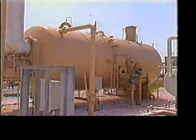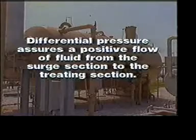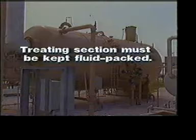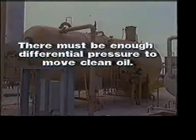There are several reasons why higher pressure is maintained in the first two sections. First, the differential pressure assures a positive flow of fluid from the surge section to the treating section. Second, the treating section must be kept fluid packed. Finally, there must be enough differential pressure to move clean oil to the storage tanks.